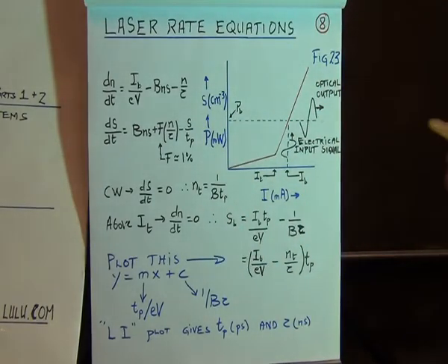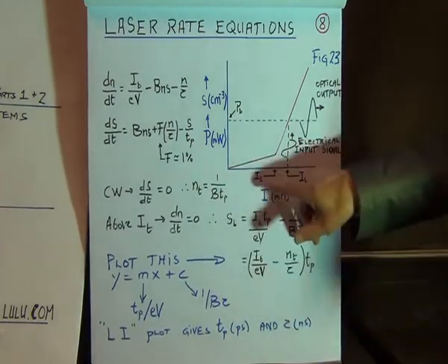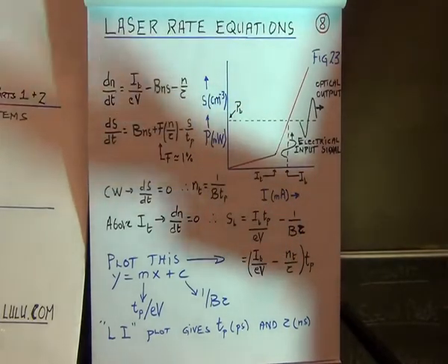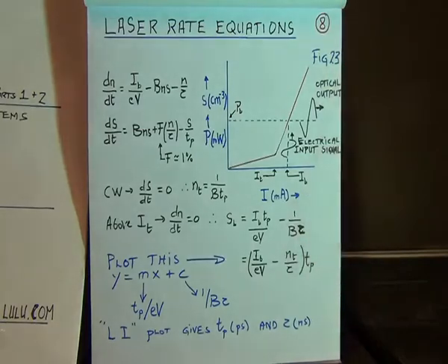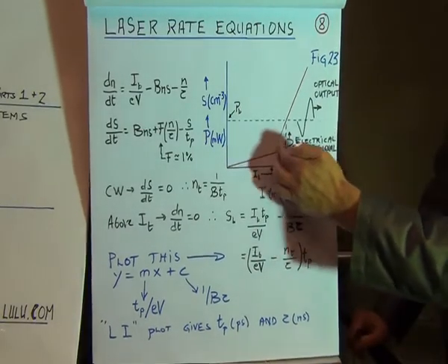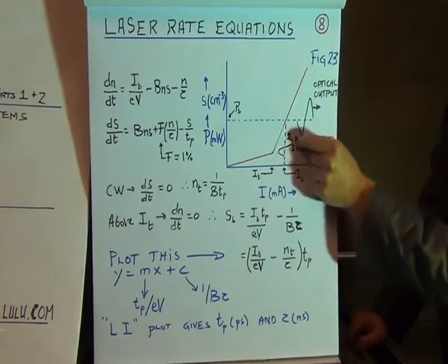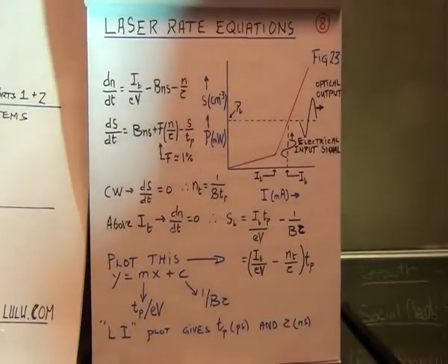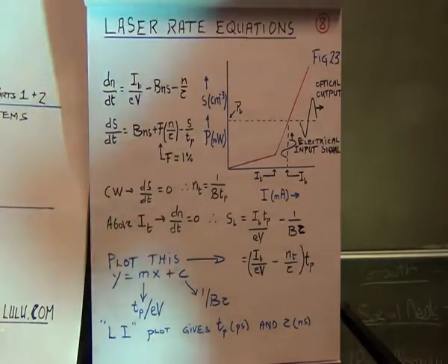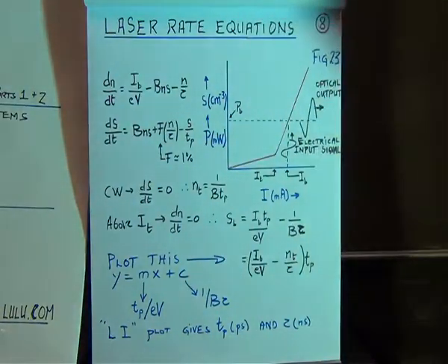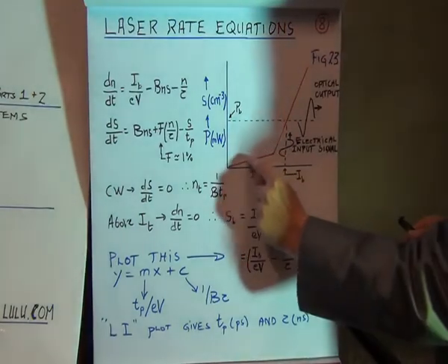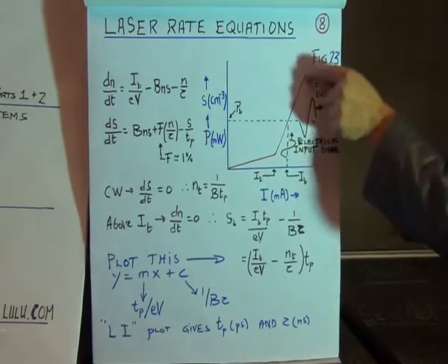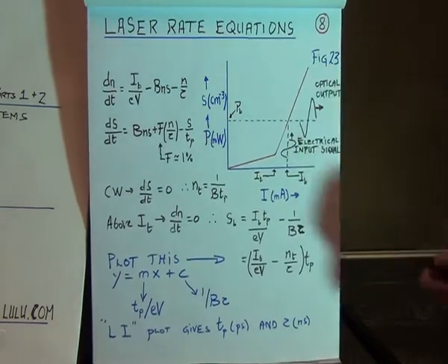If for any reason, when you're biasing it like that, the threshold changes, it can severely affect your transmission system and cause errors all over the network. For example, if the threshold moves up this way, that knee would intercept this data signal, right? And you start clipping the bottom parts of the data signal, same as diodes are used for clipping things in electrical circuits. Right? On the other hand, if it moved the other way, the threshold, and it can, the whole bias point moves way, way up, and you can move up into non-linear regions of the curve.